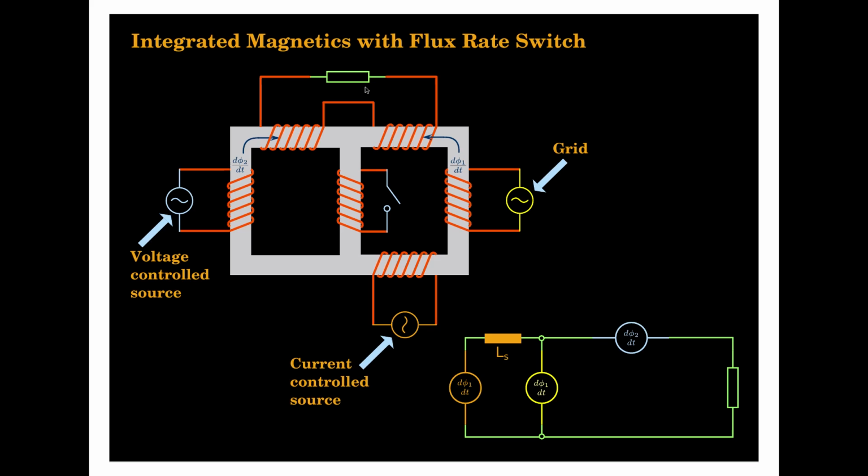So in this way, you can make it operate like a UPS. When the grid is not there, these two will be supplying to the load. When the grid is there, this will act like a series compensator and make it look like a stabilizer, and the shunt compensator, the current control, can be made to look like a var compensator.